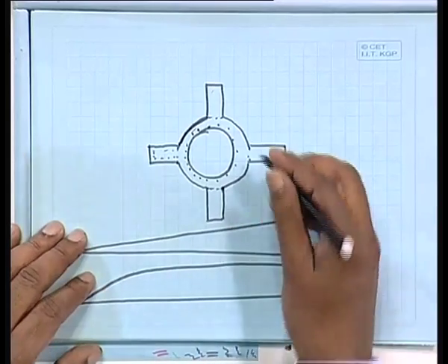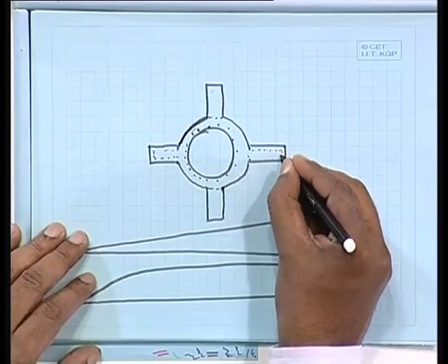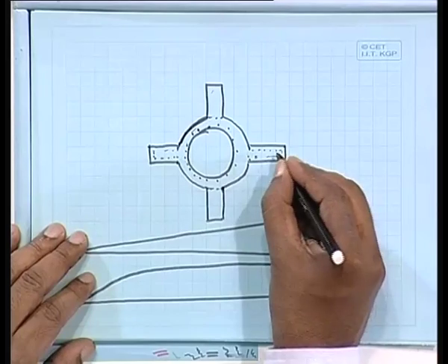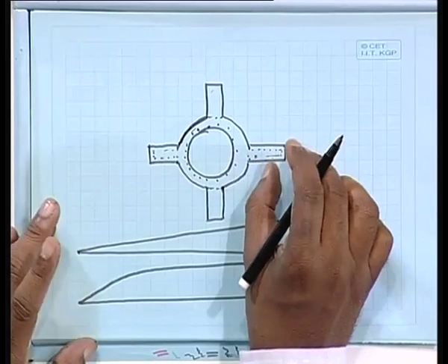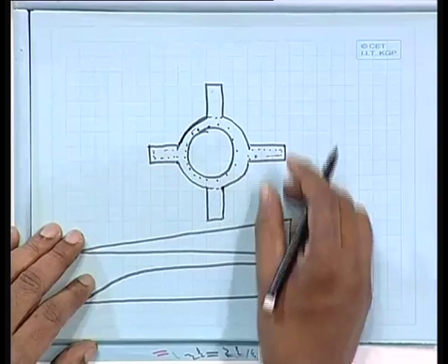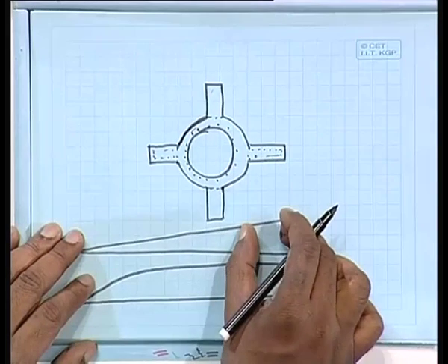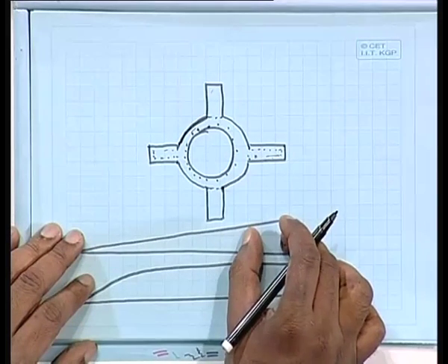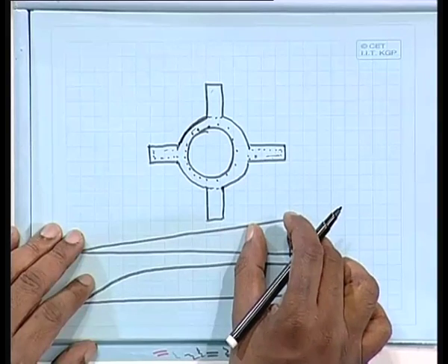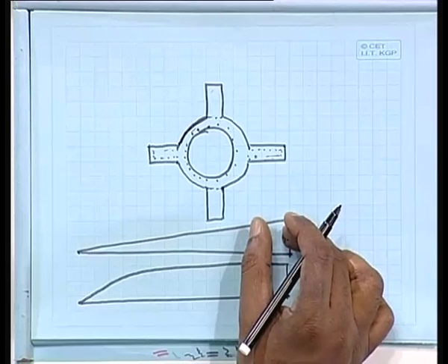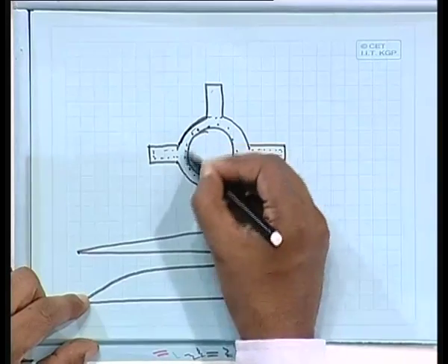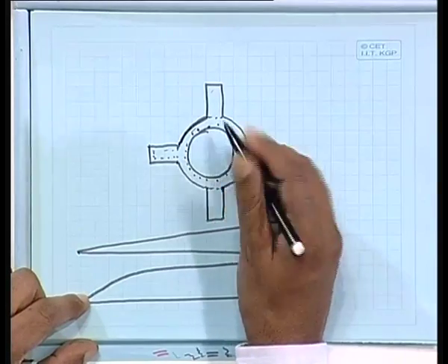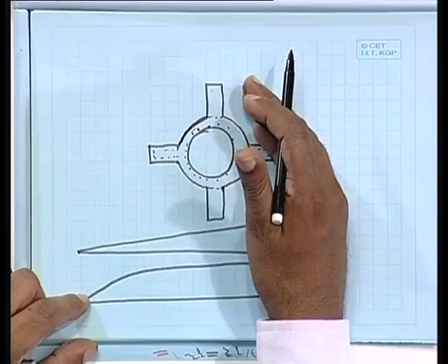For each and every component you have to make it, but that itself you can do using only rectangular and circular. A rectangle that is placed here, what is the strain diagram, what is the stress diagram, you find out that portion, you individually compute what is the moment capacity and what is the axial load capacity. For this section you find out, for this section you find out, and remove it, subtract it.